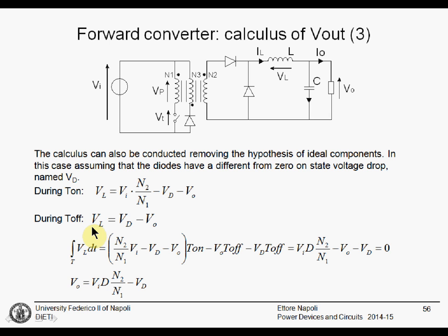During the off phase, the voltage drop on the inductor will be equal to this voltage minus VO, but this voltage is minus VD. Yes, this is minus VD.